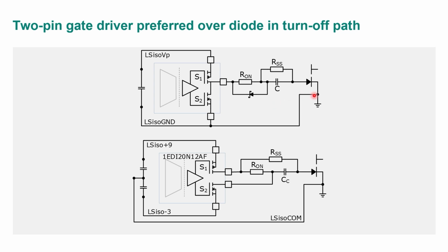Well, remember, the threshold here is only about 1 volt, maybe 1.5 volts. If I add a diode drop here, I'm now giving myself even less headroom. If this is a 0.7 volt drop, I've cut my margin in half, right? Whatever happens here, trying to pull the gate on, even if I have zero impedance here, I've already lost almost half of that through the diode.